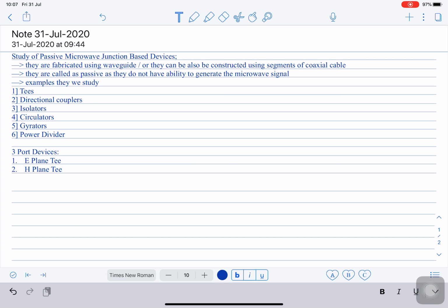Now these T devices are reciprocal circuits, and with a wide variety of applications they suffer from a limitation of lack of isolation between the output ports. Normally all the three ports are reciprocal of each other. The electrical behavior of this three port junction device can be described by an important theory. The short circuit can also be placed in one of the arms out of the three, and no power can be transferred to the other two arms.